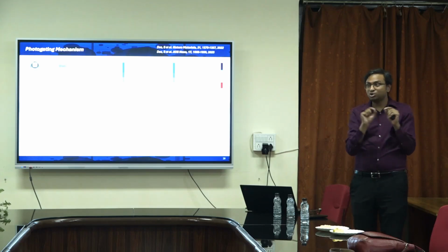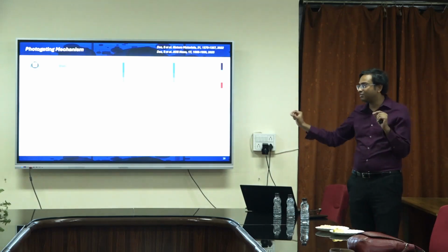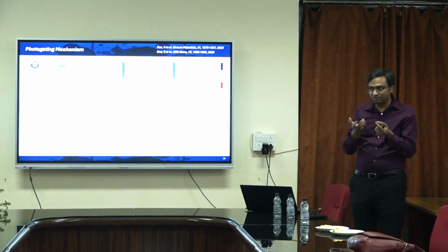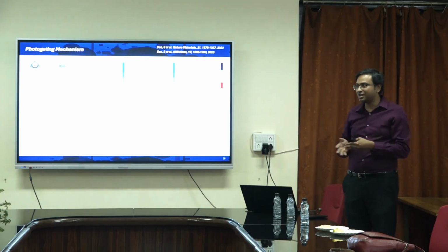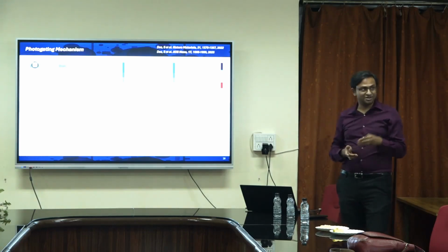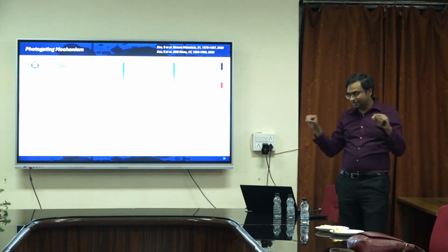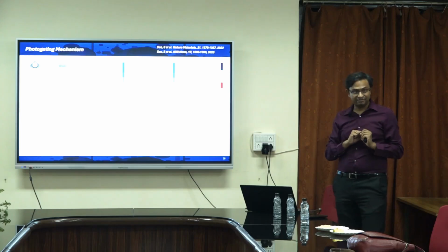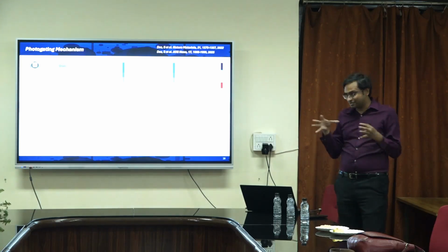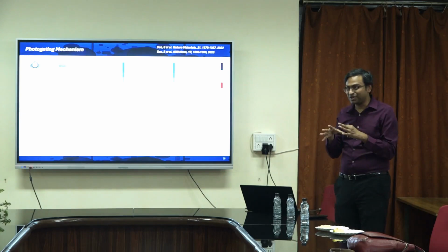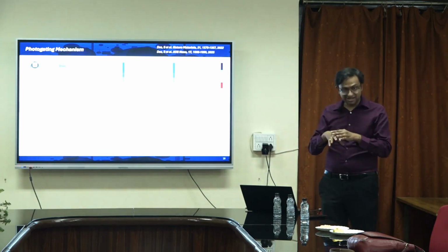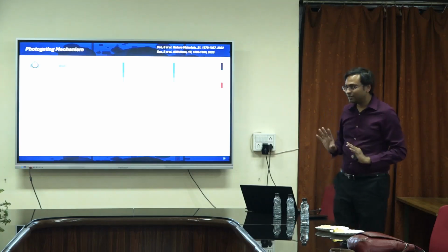This is something we generally do not do, right? I mean, you may hardly combine logic with memory, or memory devices are separate. You never combine a memory. Have you ever heard that a silicon photodiode has a memory? Right? Now we can do this with this 2D material, because we can engineer a photoactive material being gated by a flash kind of memory device. So this is now getting more into it, right? I mean, we were talking about only logic, only memory. Now memory, logic, and light all working on the same device.